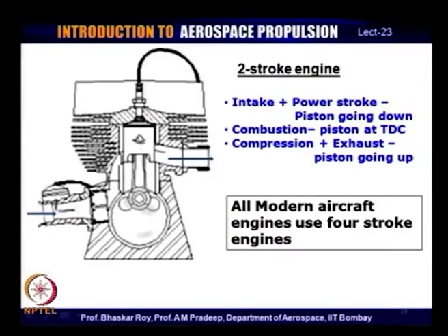When this reaches the top over here, the combustion is expected to occur, and then the power stroke could occur, and when the power stroke occurs, the intake also starts coming from this side. So, this is the side from which the intake comes, and when the compression stroke occurs, the burnt gas is simultaneously exhaled out of the system.